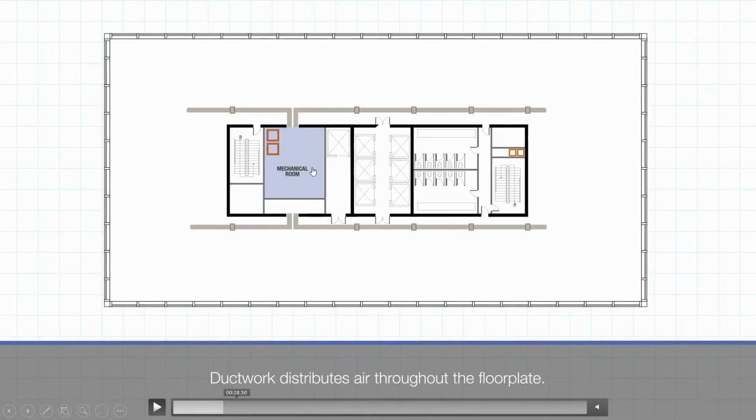All right, so in the case of the centrally located mechanical room, where you might have a horizontal compartment unit, you've got your outside air shafts that run down through the building if this is a multi-level space, and either supplies into this mechanical room or is ducted directly to the air handling unit.